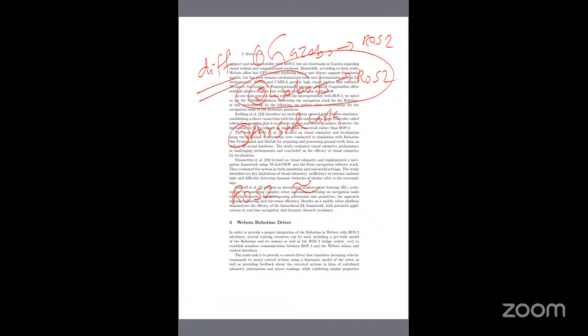They used the webots_ros2 package, the ROS 2 bridge. So ROS 2 is communicating with Webots, and Webots is also communicating with ROS 2. For example, with a ROS cmd_vel command, the Webots robot will move, or LiDAR data is published on a ROS topic.